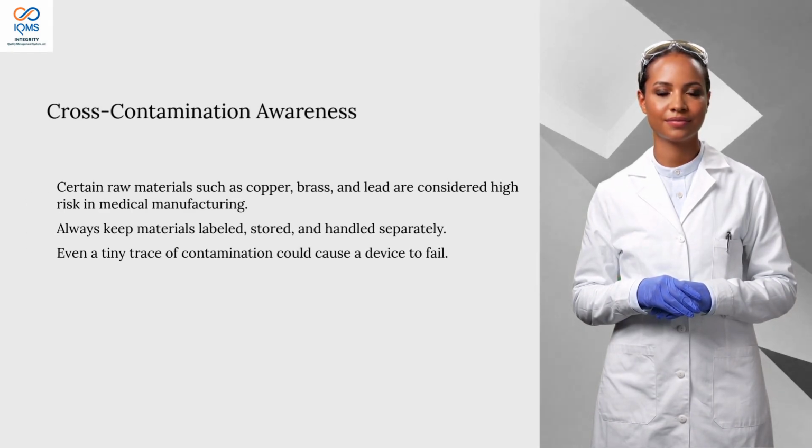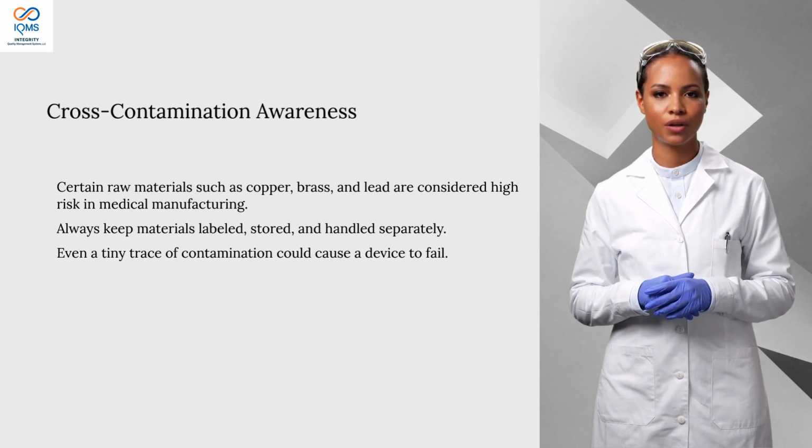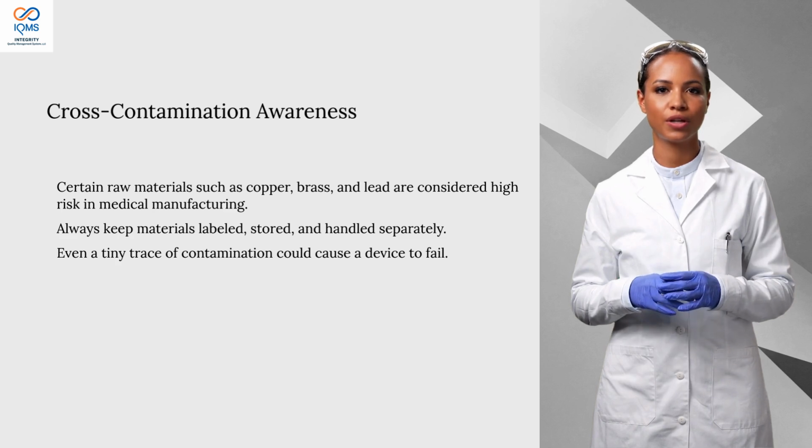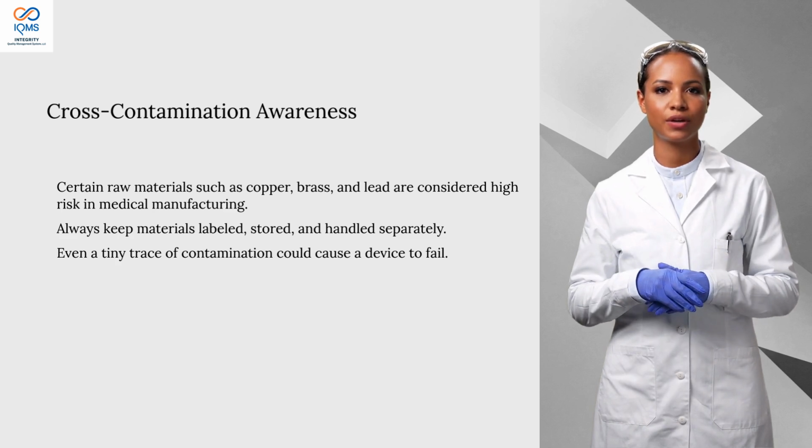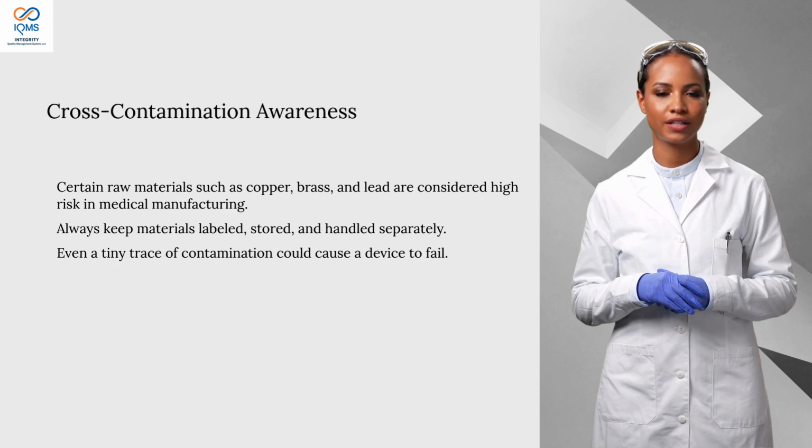Cross-contamination awareness. Certain raw materials, such as copper, brass, and lead, are considered high risk in medical manufacturing. Always keep materials labeled, stored, and handled separately. Even a tiny trace of contamination could cause a device to fail.